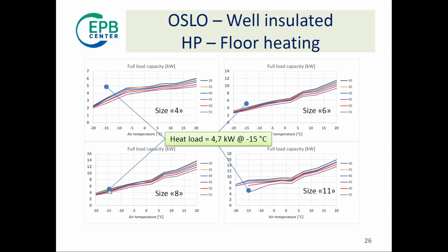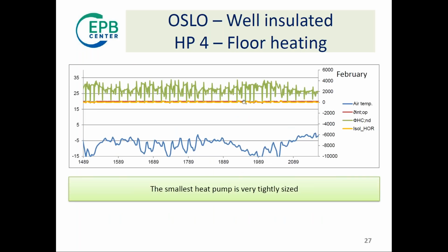And here we are at risk, because if you have low temperature, it's okay. If you have high temperature, even with high temperature, you would not match it. So you should need even the size 11. Well, I use a size 4 and just have a look at what happens. And of course, as we can expect with the smallest heat pump, with continuous operation in that case, you will see that of course you have some discomfort, but most of the discomfort is just linked to the reload of the domestic hot water storage, not really on the fact that the heat pump doesn't match the load for heating. Actually, it's nearly matched.